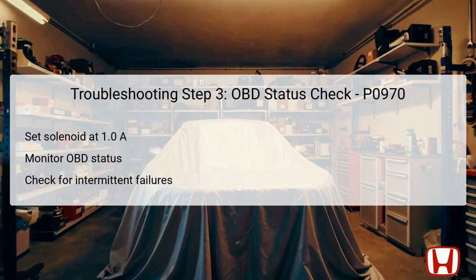After setting parameters, monitor the OBD status displayed on the HDS. If the status indicates a failed response, this confirms a recurring issue that requires immediate attention. However, if it states passed, it suggests potential intermittent failure, signaling the need to check connections and terminals between the solenoid and the PCM.